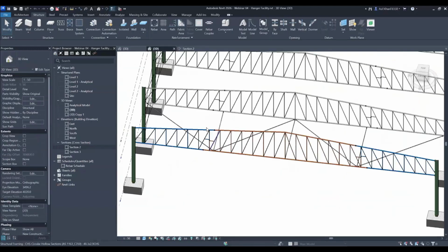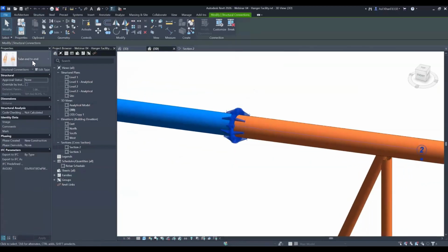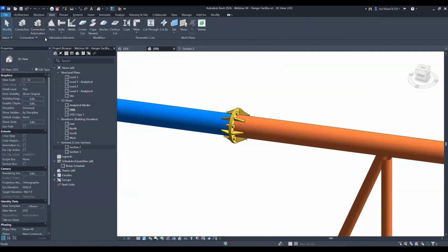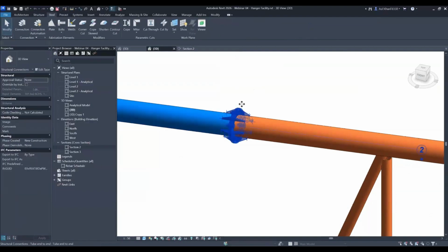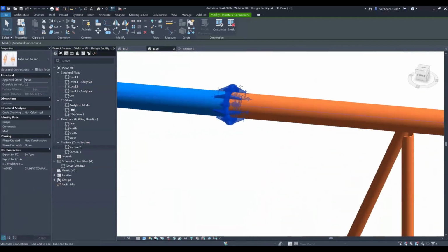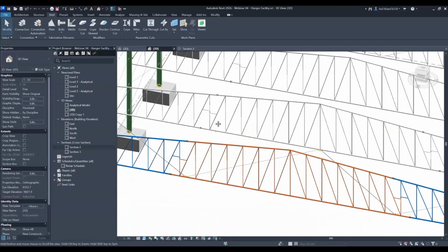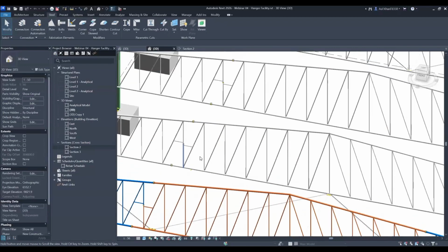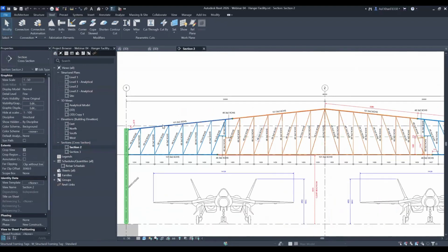And then in the 3D view, you can already see we have some cool connection, which is the tube end to end. This is the same connection system I'm using. I'm not using any kind of different method. As you can see over here, everything is loaded. So tube end-to-end connection exists here. So you just have to explore, select, and apply. And there it is. My tube connection is applied. So I also replicate the same thing over four different places of each truss, as you can see. And I have just colored this up so that the things can be understood by the fabricator when they are fabricating, that okay, this is a different part and that's the other part.